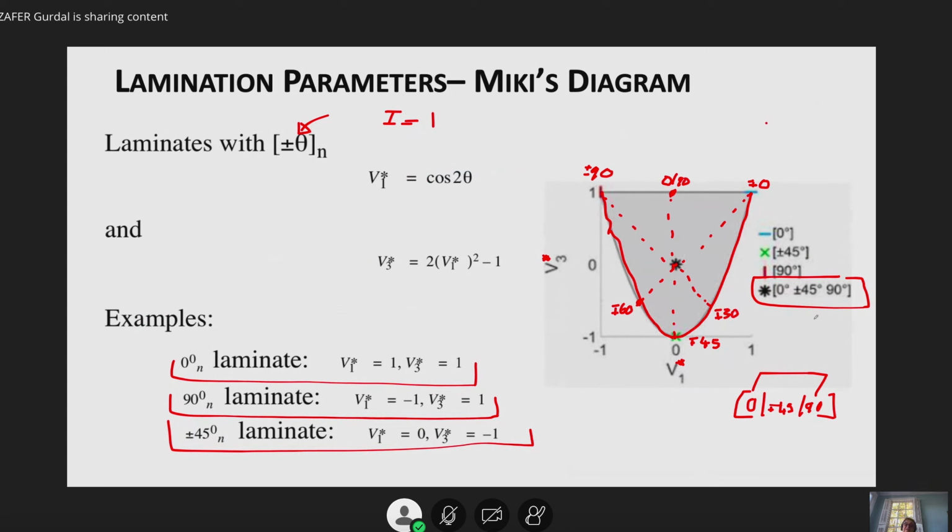Now, this basically tells us something else. There are potentially infinitely many laminates that are quasi-isotropic, as long as you can determine their proper ratio going from one end to another. So if I'm going from here to here, and if I know what this angle is, and what this angle is, I can use equal amounts of those angles and find the quasi-isotropic laminate here.